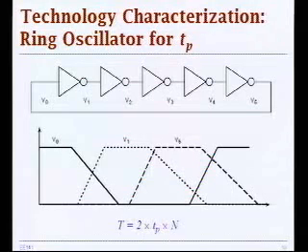but we had too many simplifications in this case. Number one is we have a very simple gate, just a simple inverting function, and number 2, we assume fan out of 1, unity fan out across the structure, which doesn't really give us a realistic estimate of the speed, the clock speed and performance at the higher layers in design abstraction. So normally the clock speed is about 20 times slower than this propagation delay of a single inverter in a ring oscillator configuration. Question? Yes.